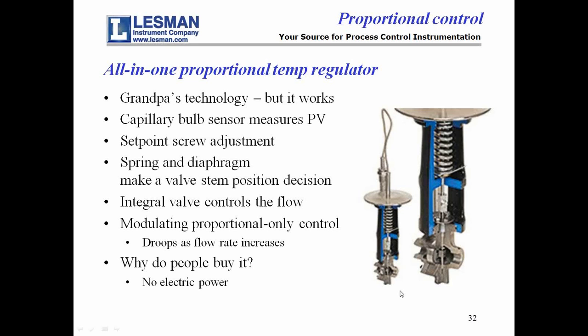And you go, why would anybody use something as antique as that? And the question is, you don't need electric power for it. There are a number of places that have a steam line within 50 feet that they can use to get their heat, but they don't have any electric power there to run an electronic controller, or they might even lack instrument air out there to drive the actuator on the valve. So there are reasons why people still buy this kind of stuff.